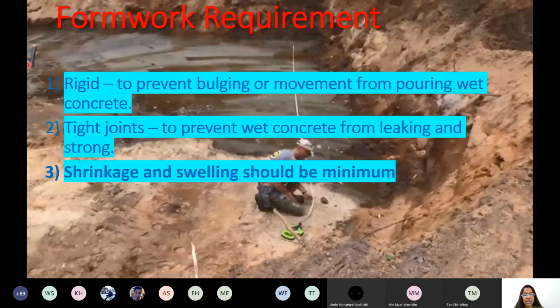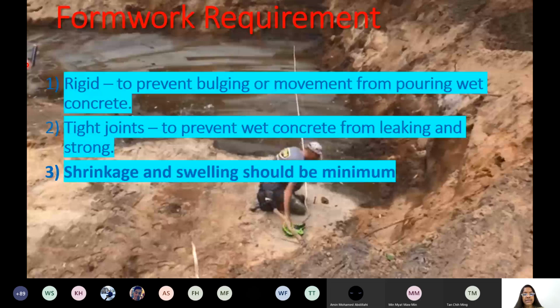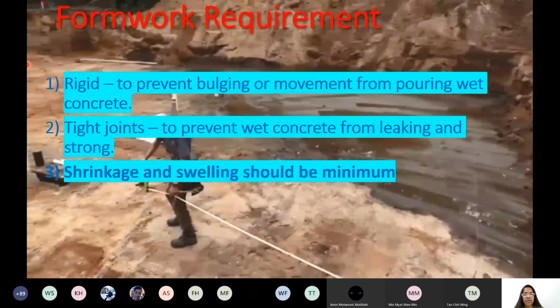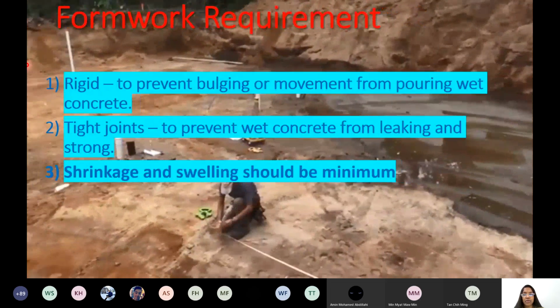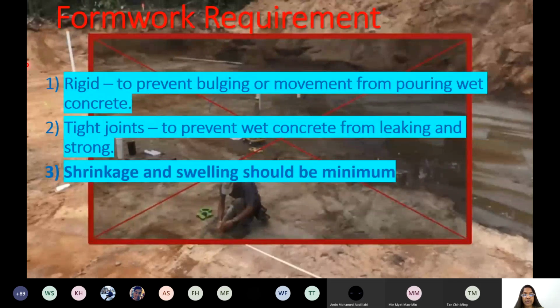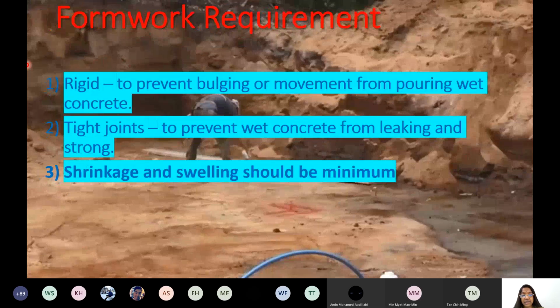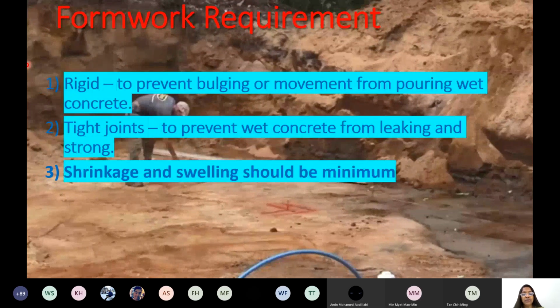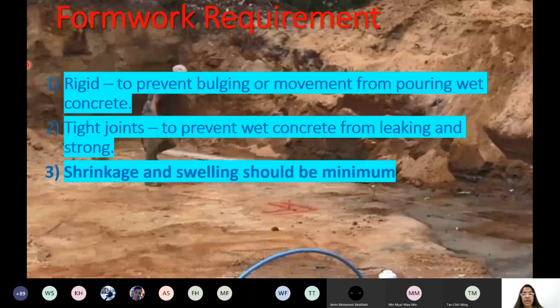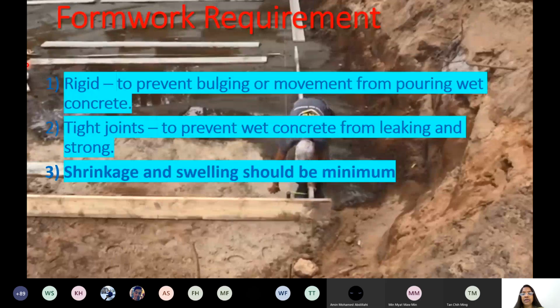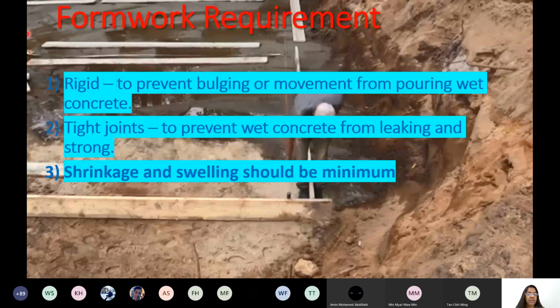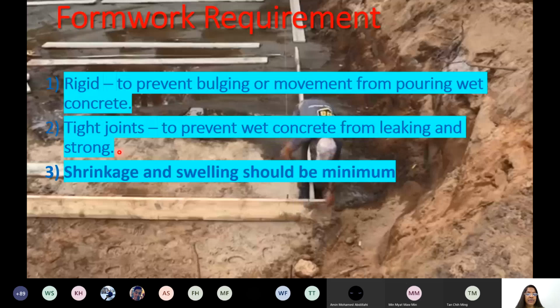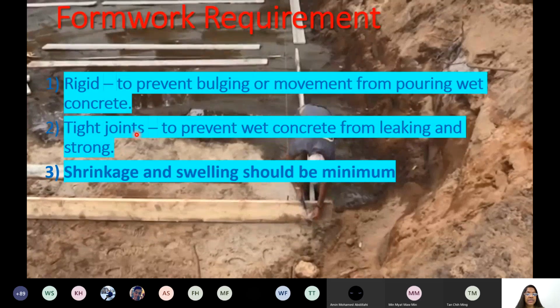It's not one panel which is used in formwork. It's a continuous panel or a fabricated one, modular, or otherwise a network of panels that are jointed by nails or by resins. Plywood, if you take, is all connected by resins. So there are different panels which are put together to form your formwork for concreting a slab or a beam or column. So the joints should be taken care of. Your formwork should have tight joints, otherwise it will be leaking.